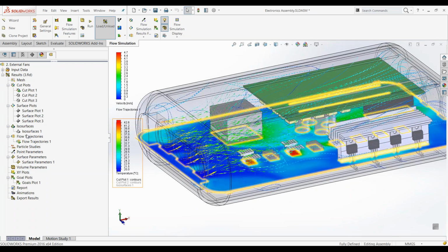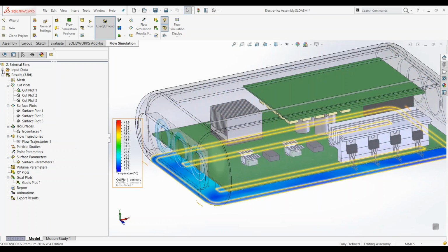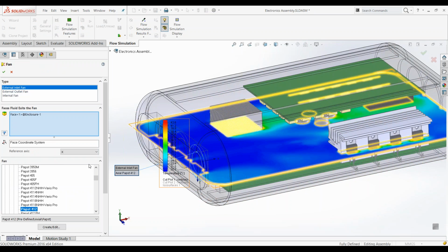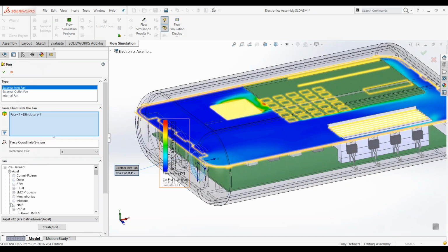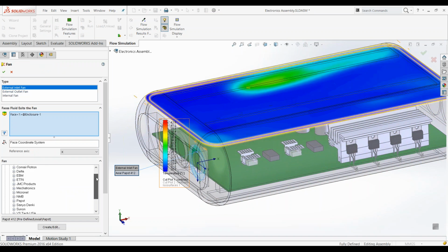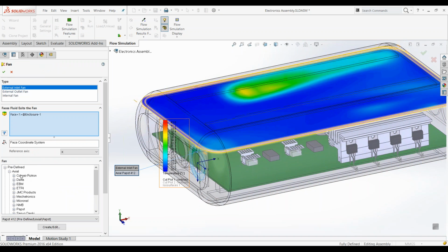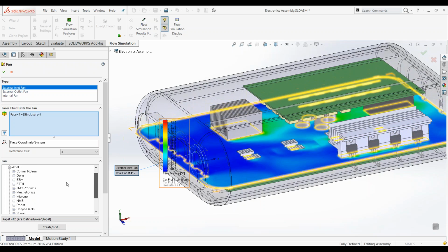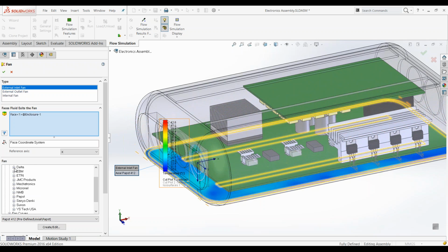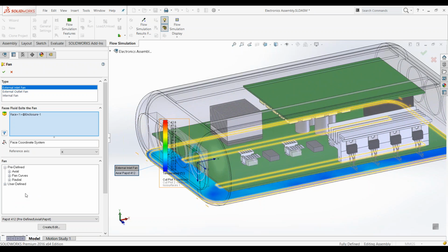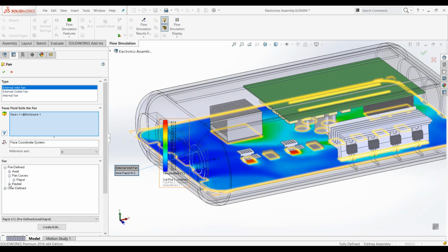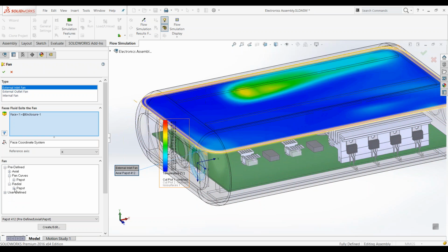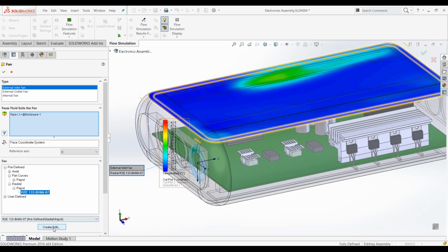I would also like to take the opportunity here to go into understanding what kind of fan curve is required. In Flow, we already have some predefined fan curve data available here. These are from different suppliers, and we can also always insert our own fan database into it.